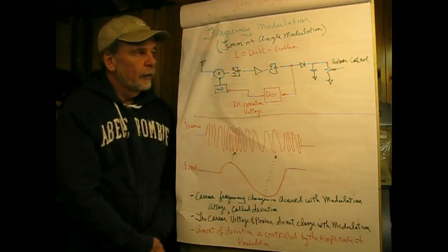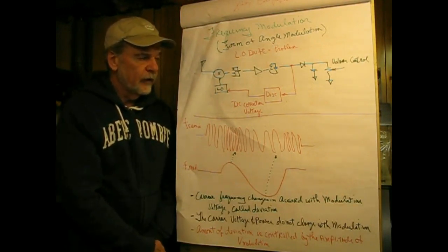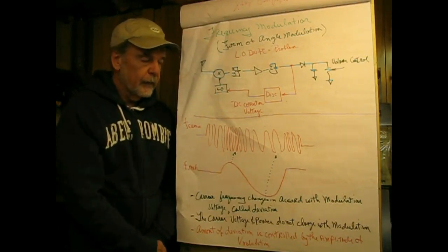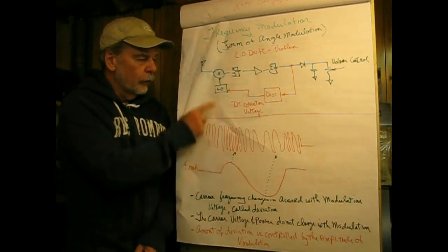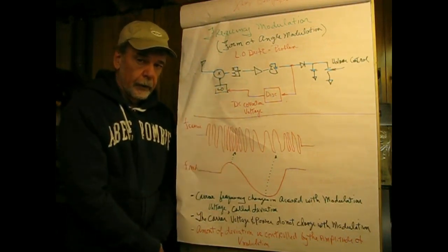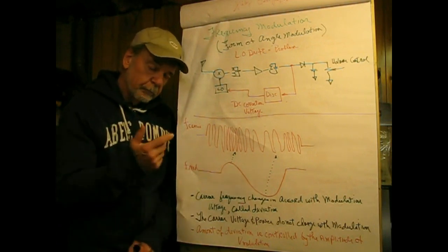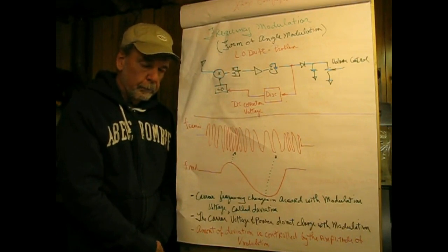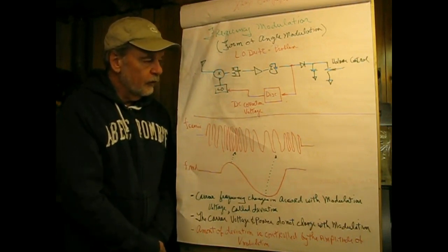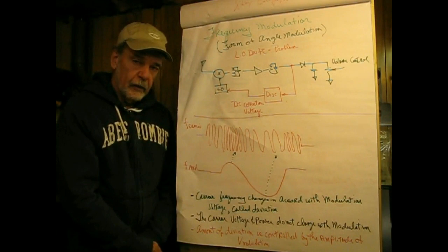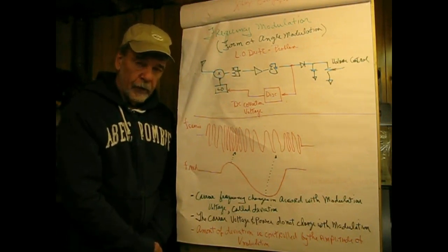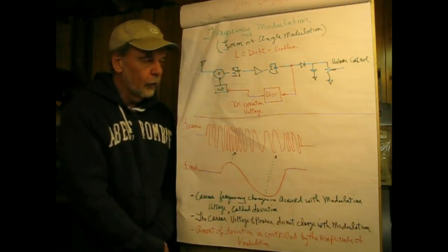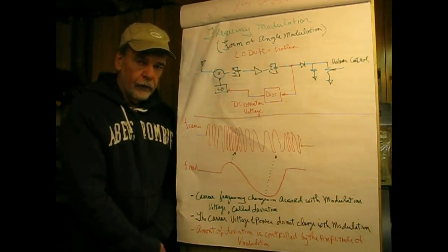Now, historically, the way this came about is that in the days of old, and even in the days of contemporary transistor radios, it's very critical that the local oscillator be exactly where it should be, which is in high side injection, the intermediate frequency above the station that's tuned. Especially in the days of old, where you're dealing with vacuum tubes which have filaments which get quite warm, plus the electronics gets quite warm also, the local oscillator had a tendency to drift.